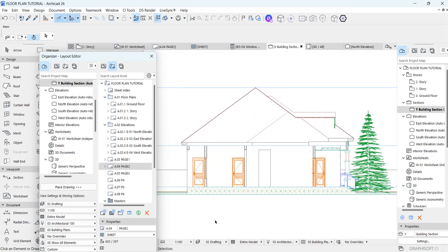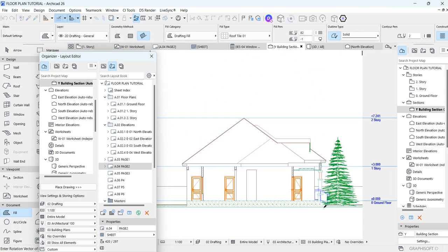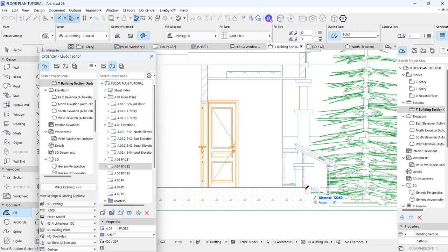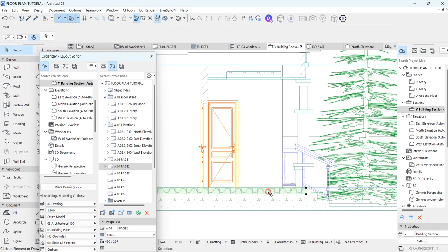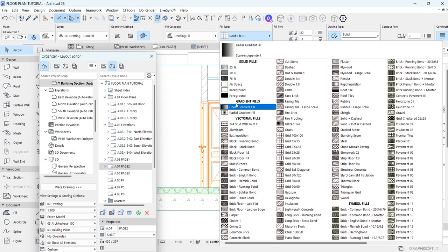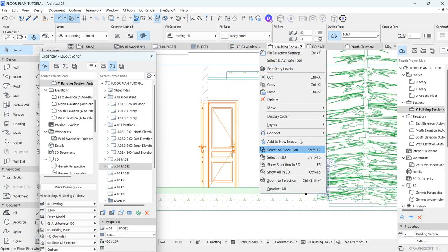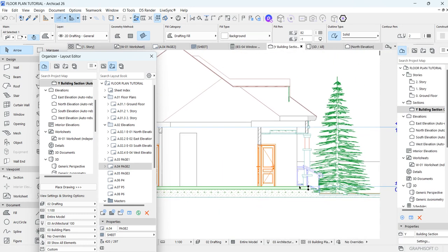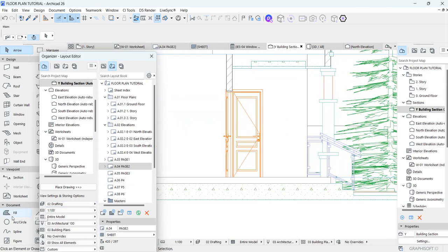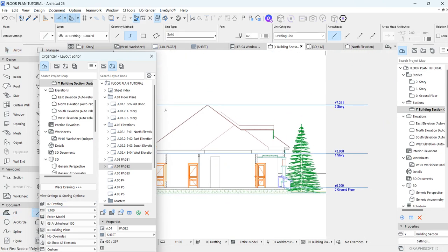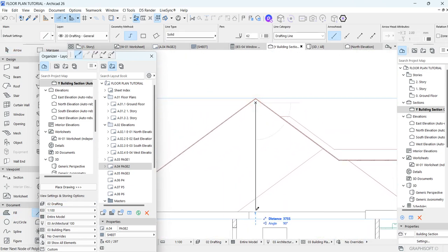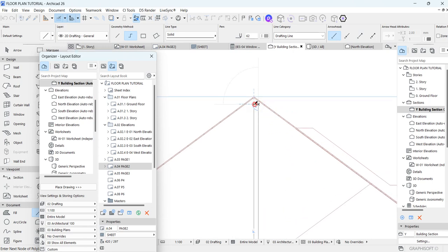So imagine if I've detailed my section with my fill tool and line tool, putting in my composite slab of 150, overriding it, showing it at the front. Then I've used my line tool to detail my roof members, all that stuff. I think I've done a video on how to detail your section.